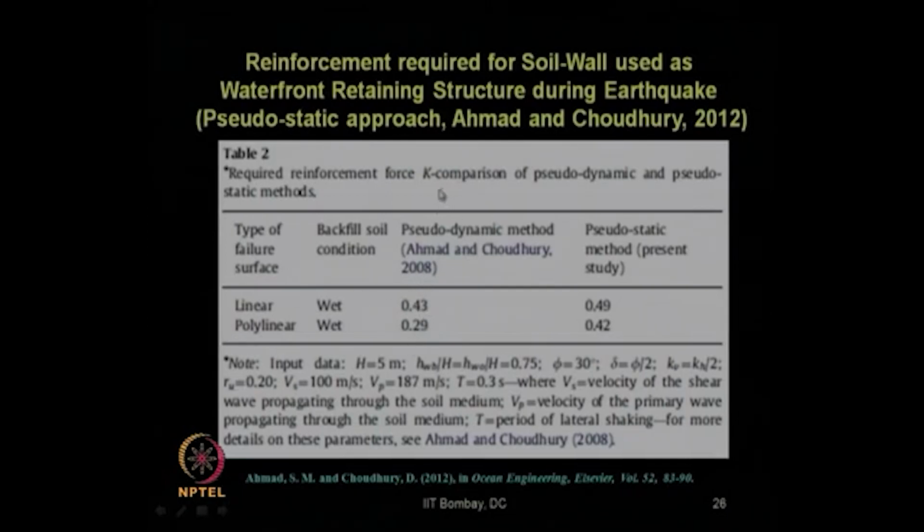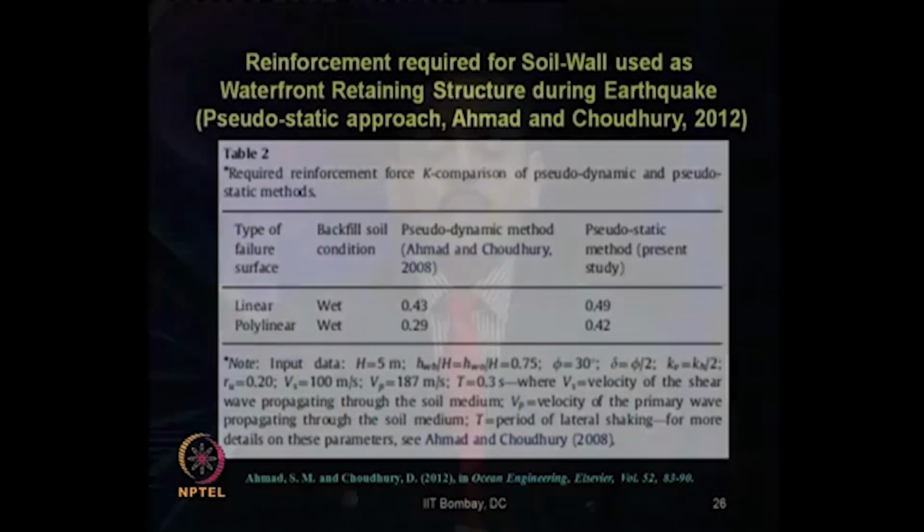You can see over here the value of K, that is the reinforcement strength required, as far as the pseudodynamic approach and the pseudostatic method are concerned. You can see the pseudostatic method in this case is giving a higher value. So, it is not always necessary that pseudodynamic will give the lowest possible value. It can depend on the various input parameters.